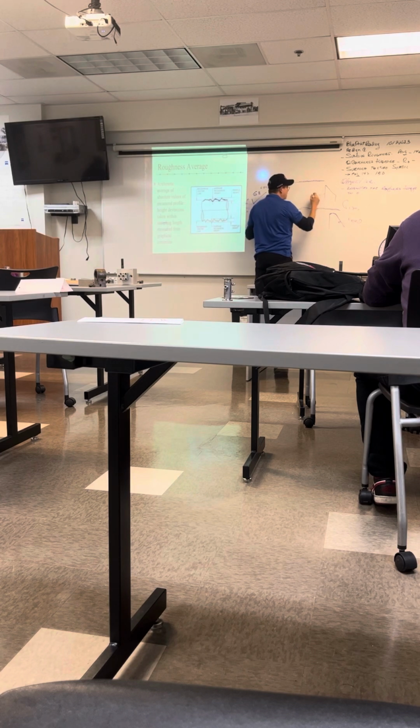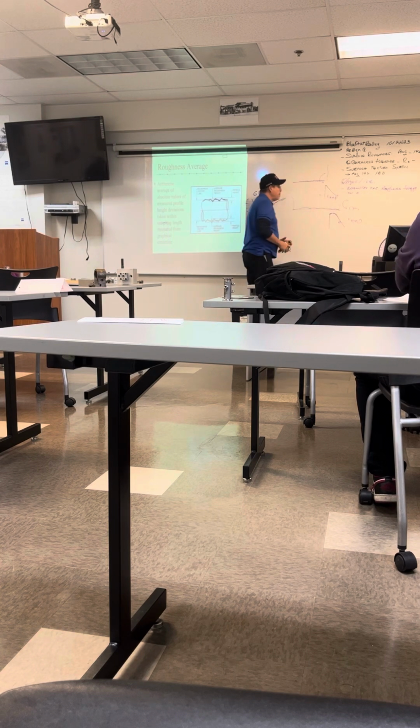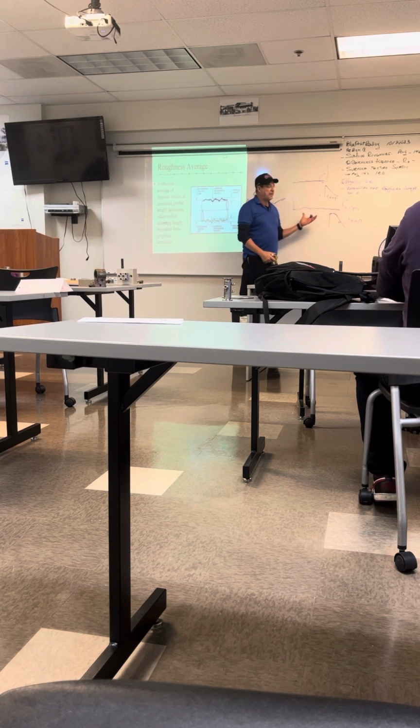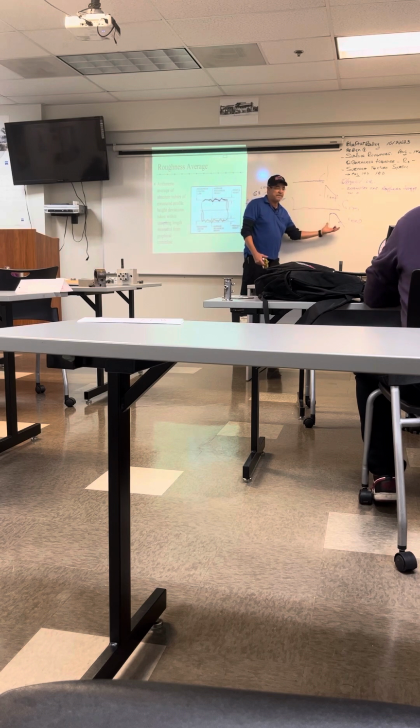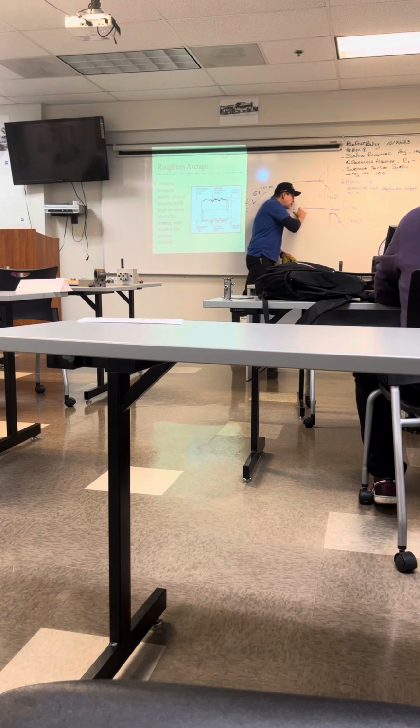When you combine the RPM and the feed, imagine this is the part, right? And this is the tool bit, and that's the feed. Therefore, when you combine the feed and the RPM, increasing the RPM and reducing the feed, you probably get a cut that is more smooth because it goes more even, so it's more nice.